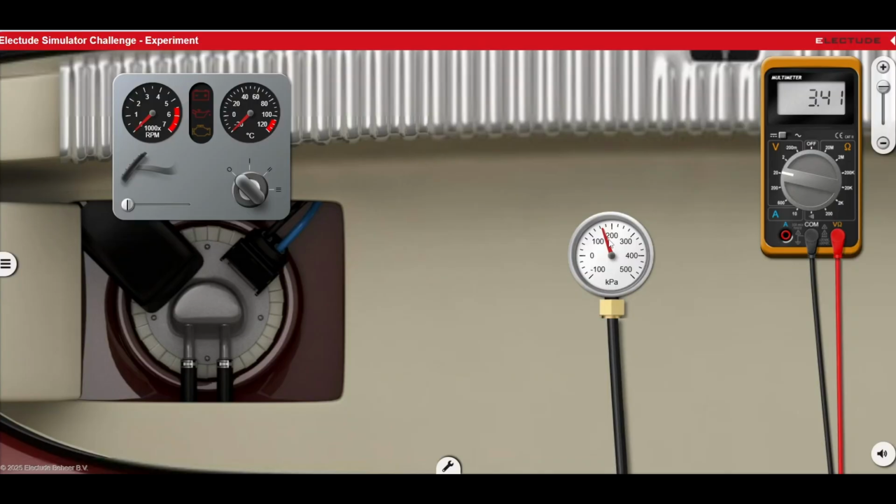And that's normal. What you don't want is to prime like this, switch off, and then the fuel pressure immediately also falls to zero. It means there is a valve in the pump that is faulty. It will not stop the engine running, but it will lead to long crank times. So let me disconnect the pump. You can see the pressure is still there, but I'm going to crank the engine. That will consume the fuel in the fuel lines, and the pressure will fall almost immediately. Let's try that.